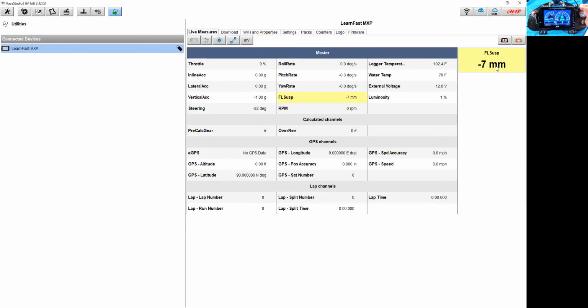Yep. Everything looks good. So typically the most common thing we see with suspension sensors are these linear pots. It can be done with rotary if you have maybe a Formula car with the bell crank, or you get pretty creative and you mount it on the A-arm so it rotates with it. Popular one, and I think Roger was one of the first people I heard it with, is he has a great story about taking a suspension position off of, what was the car, Roger?